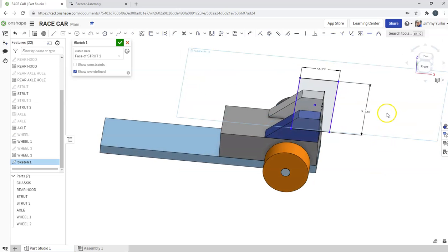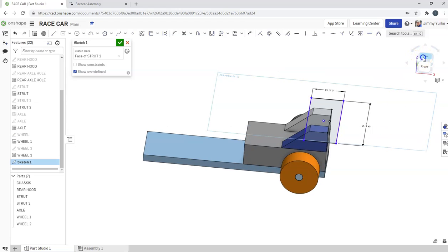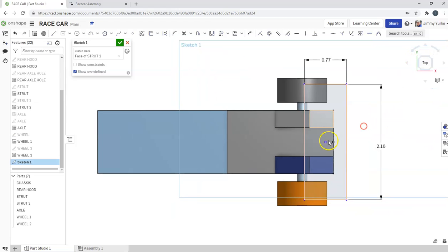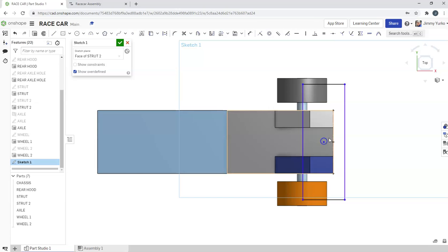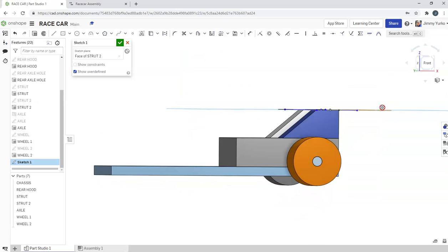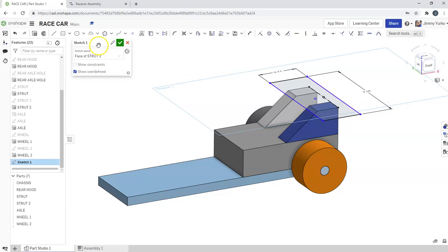If you want to slide this thing fore and aft, you can just by clicking on the center point of the rectangle. You can slide that around. Once you let it go on one of these grippy points, though, it's going to be stuck to it. You'd have to delete that constraint. So I would avoid getting it snapped directly onto a point like that, and then you have to delete it and try it again. No big deal. All right, there you go. There's the spoiler outline.